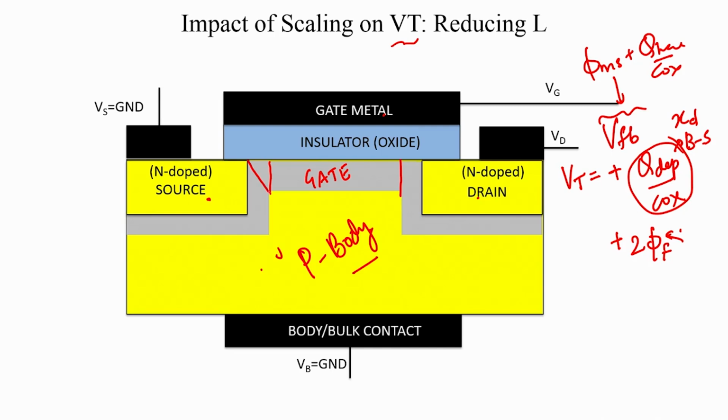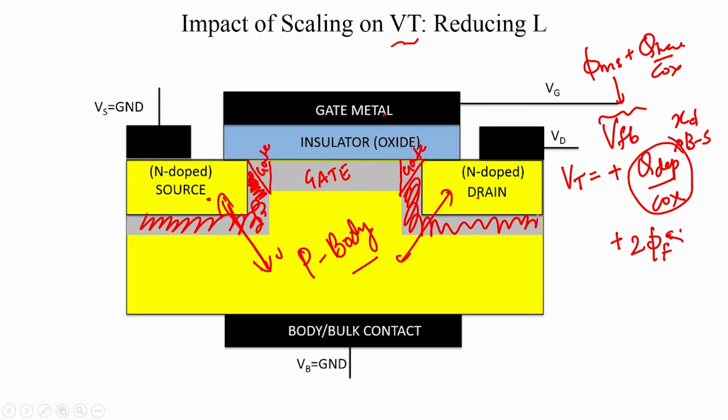Half of this region is also the job of the gate, because this region is shared between the PN junction and the gate, and the remainder half and all these regions are all depleted by this PN junction between source, drain and bulk. So, all these are jobs of the PN junction. Essentially all the gate charge goes into depleting that particular region.